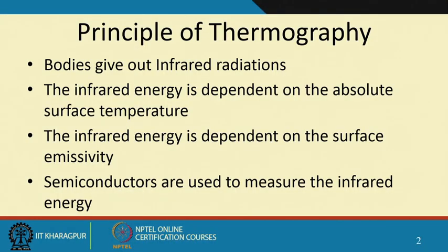Imagine, in the last class I was just mentioning condition monitoring of switchgears. Imagine you have a large transmission tower, and it is carrying a conductor with a switchgear, and some sort of contact it has to make. Of course, there are insulators, I am not going to talk about them. Suppose there is a loose contact. So, with a loose contact there will be a lot of sparking, and there will be heat generation.